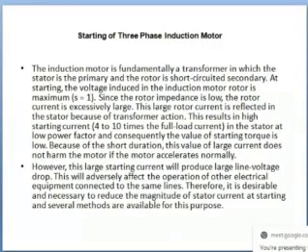Previously, we have studied induction motor, transformer and DC machine, where we have used a starter for the DC machine, but we don't use a starter for the transformer because the transformer is a static, purely electrical device with no rotating part in it. That's why, as we all know, the electrical time constant is very much less than the mechanical time constant. So the back EMF in a transformer takes very little time to generate.